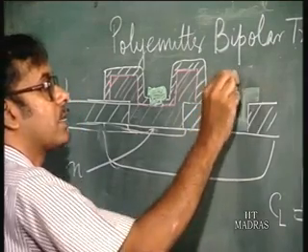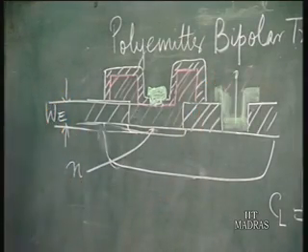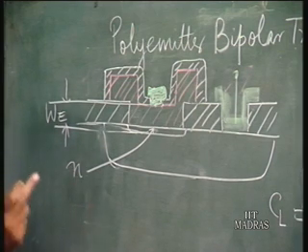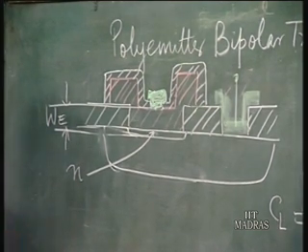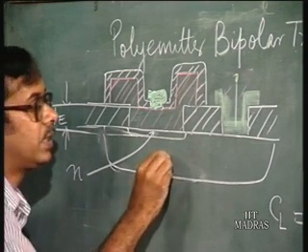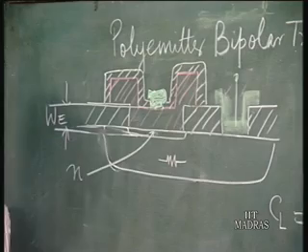So this is the base contact. Now if you look at the values of the resistances, RL and RE are external resistances. Now you have RBI and RBX. RBI is the intrinsic base resistance, which is usually this part of the resistance, that is intrinsic.